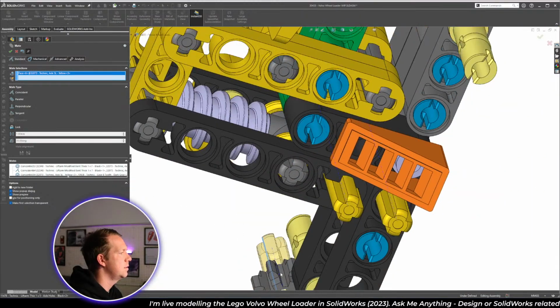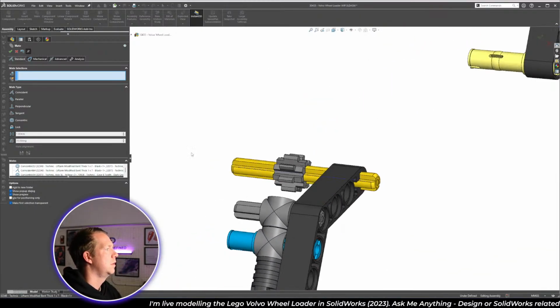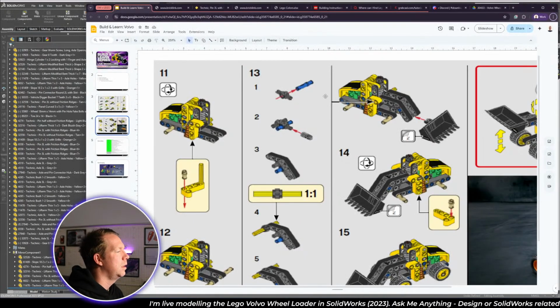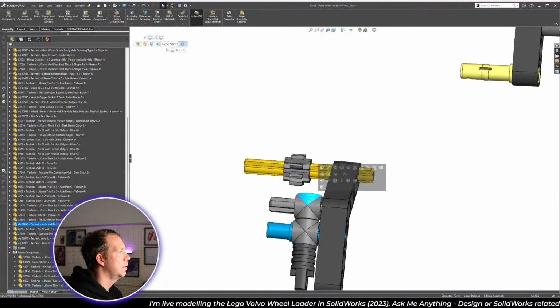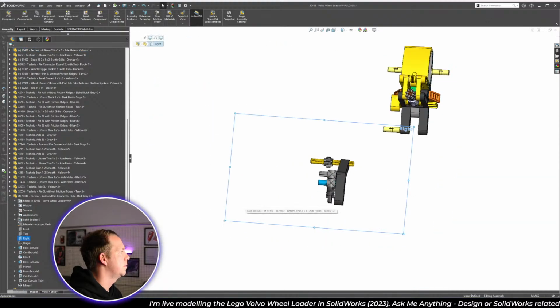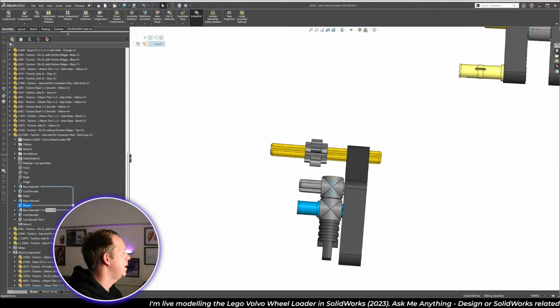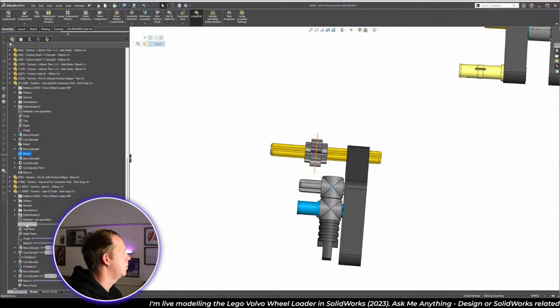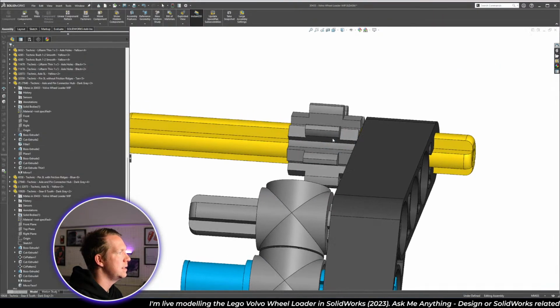Again, get these faces parallel. And the gear is going to sit right in the middle. So I've not made it to the right plane yet. What I'm going to do is use the front plane of that part, it's plane one of that part, and what will be the front plane of the gear to get them coincident. That way that gear stays in the middle.